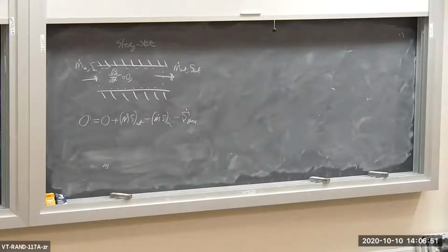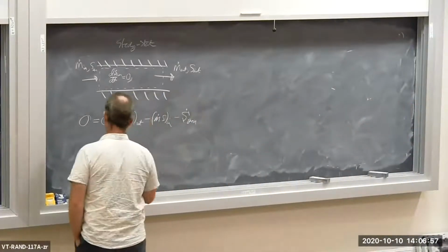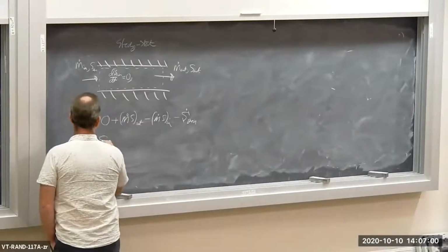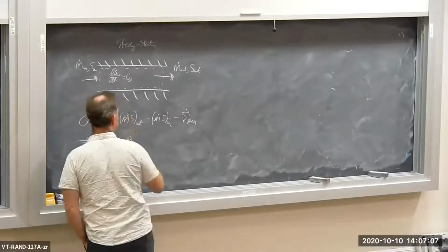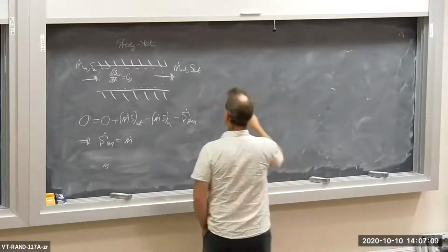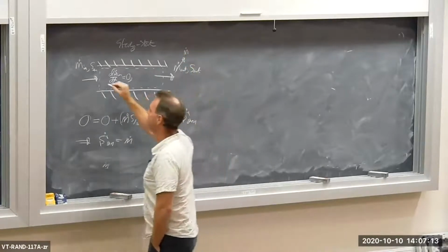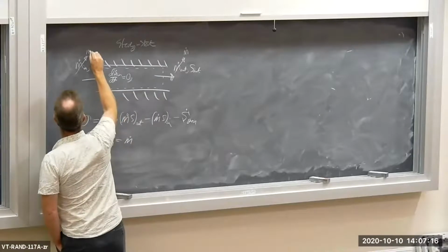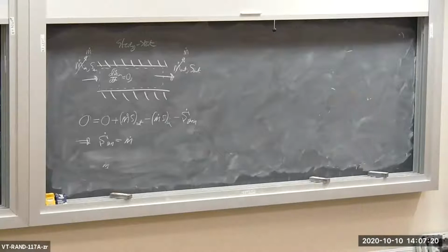Now I'm going to take the S dot gen term and put it over on the left-hand side of the equation and group together my mass flow terms. S dot gen equals m dot. If we apply the mass balance to the single inlet, single outlet, steady state case, m dot out is equal to m dot in, which is just m dot, since dm CV dt is 0.